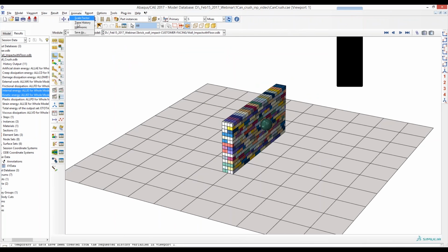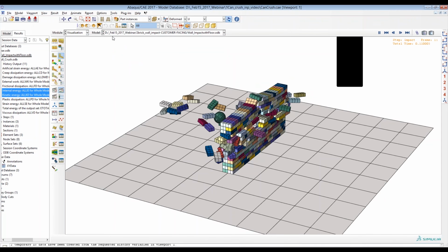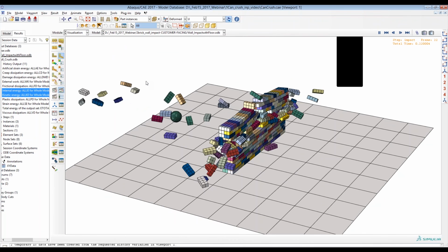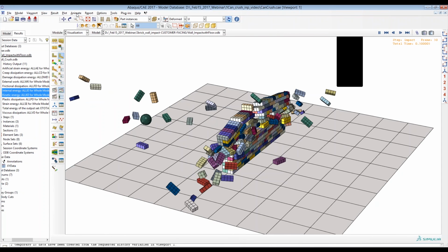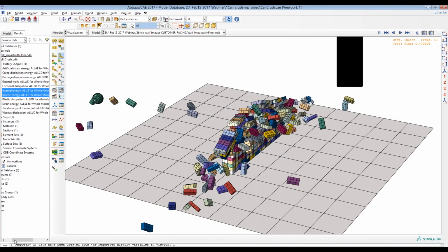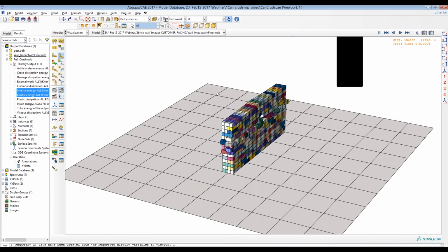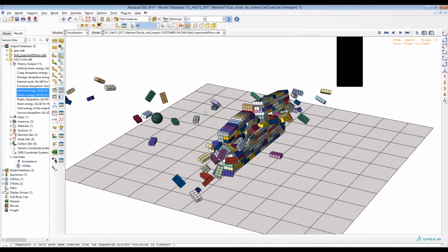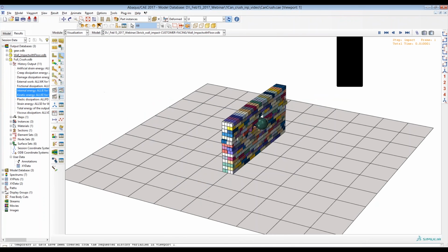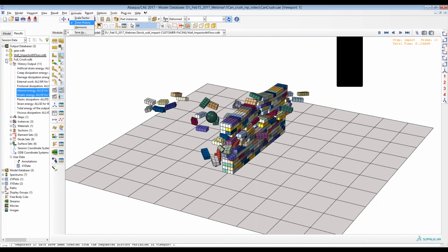So we can choose how many of our steps are active when we visualize these things, if we want the animation to go real quick without a lot of resolution through time. Once it goes through mining the rendering data from the first pass of the output database, you can see that it shows the animation quite quickly. And if we want to come in and look at what some of these output parameters are, ahead of time I defined a parameter to track some of the spatial displacement of the ball and acceleration and velocity.